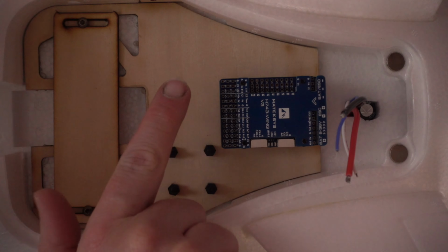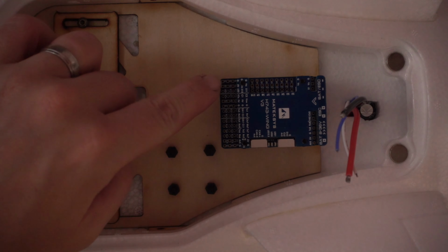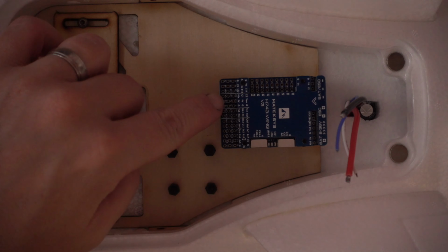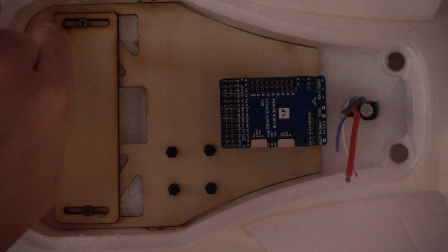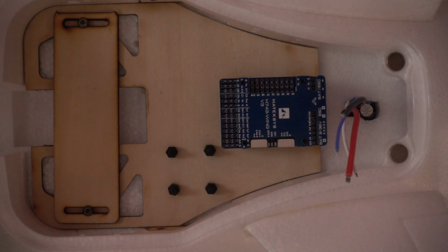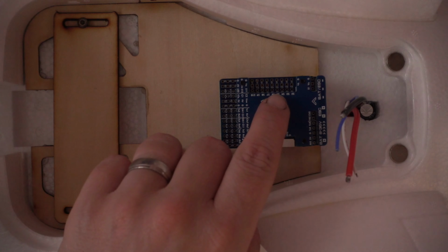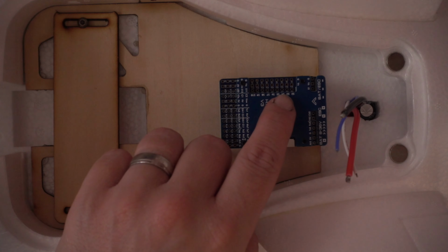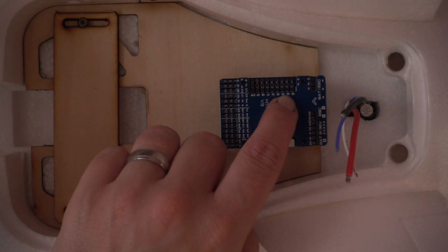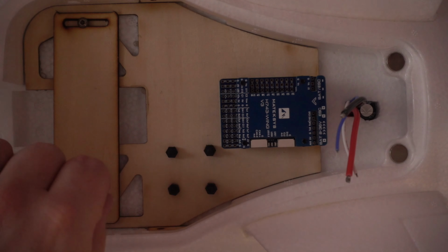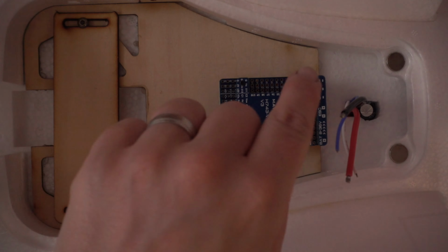So we've got a nice short lead here for our power. The video stuff, what I'm going to do is take it from this side, so this block here, but I will take it out around this side and down this side of the fuselage so it's away from the power. And for the servos, I'm actually going to put pin headers onto S3 and S4 so we can just put the wing in and just plug them in.